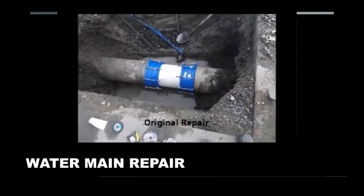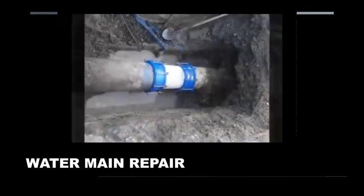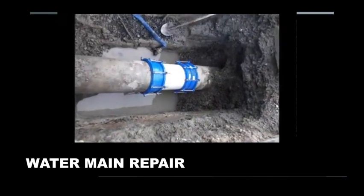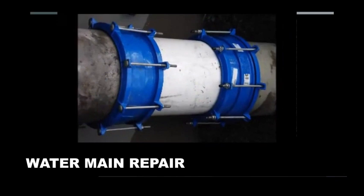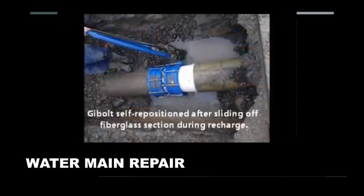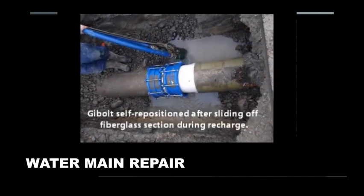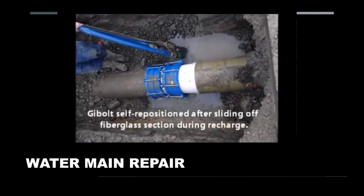They've just cut that section out, put a new bit in and two new gibault couplings to go between the different materials. They've got a big thick rubber ring on them, and when you tighten them up, they compress the ring onto the pipe. But when they turned it back on with water, it actually slid off out of position, so that wasn't too flash. So they had another go.